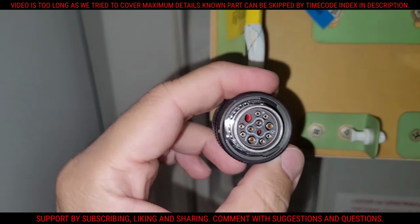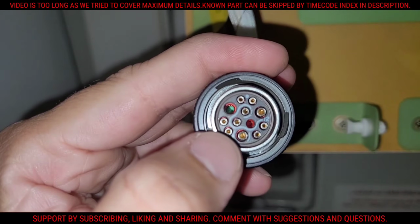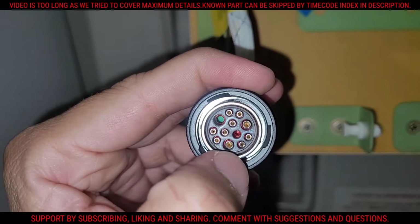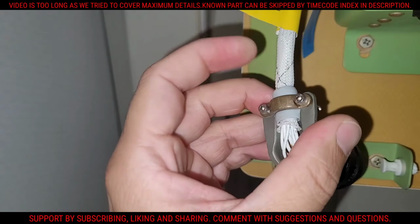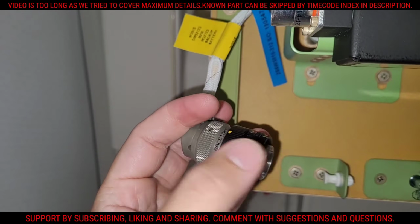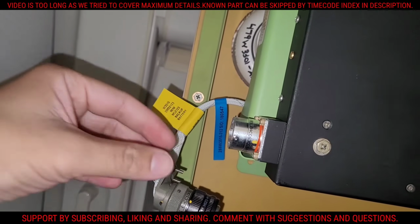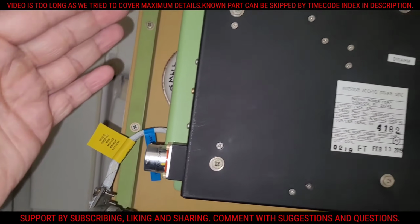If we are supposed to change any contacts, we'll find out the part number of the contacts inside. You can see there are two types of contacts and the configuration is also different. We'll check out what is the wire number, the part number for this wire, the part number for the contact, and also confirm the part number of this connector and where this wire is going, the other end.